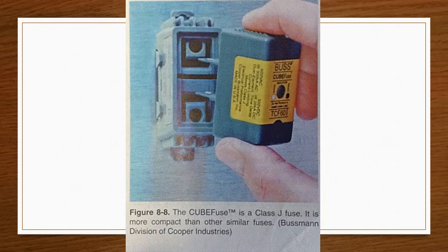Just as an interlude, when they talk about 10,000 amperes and 200,000 amperes, that is the interrupting rating, sometimes called short circuit rating. Basically, that is the maximum amount of amperes that the fuse will open if it happened to go through the fuse, which is very rare and unlikely. That is the amount of amperes that the fuse is physically able to break, not necessarily the protection provided for the circuit, which is much lower than that. It should be 15, 20, 30 amp.